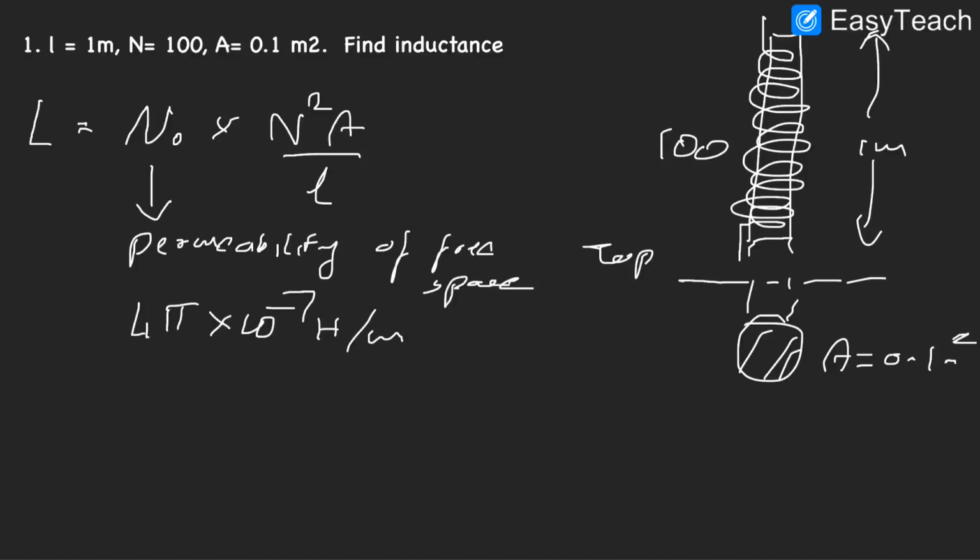So you have your ferromagnetic materials like iron, which allow a lot of field lines to pass through them. And you have all other materials which allow magnetic field lines to pass through them to a relatively low extent. So this is a measure of how many field lines a material allows to pass through it. Alright, so in our problem, it's air core. So basically, this core is hollow. There's nothing but air. So this is a measure of how many magnetic field lines regular air or free space allows to pass through it.